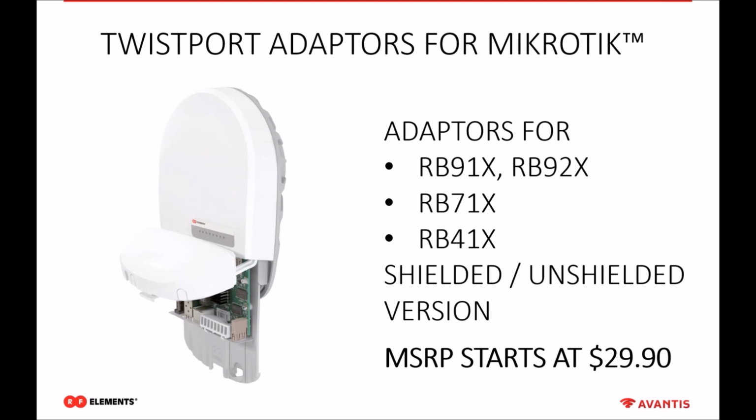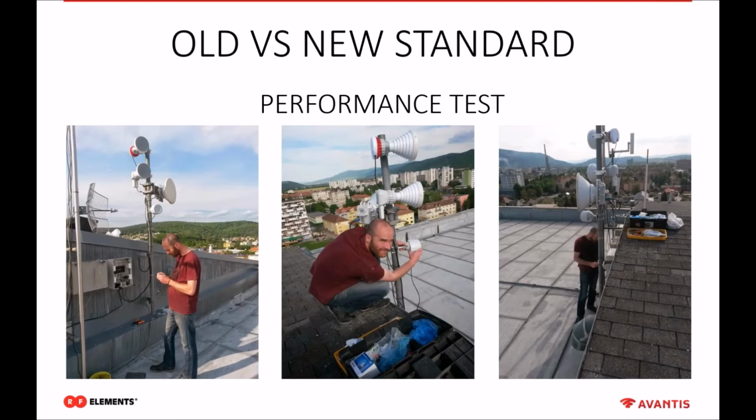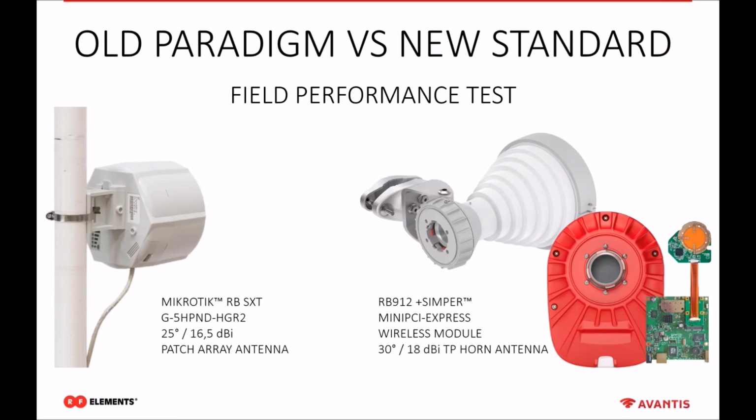So we did one performance test. We call it old versus new standard, because we compare twist-port antennas of symmetrical sector and traditional devices. To be more detailed, in this field performance test we created two links. One link we created with a MikroTik SXT. Here you have the exact same model on both sides, so on both ends of the link was this device.